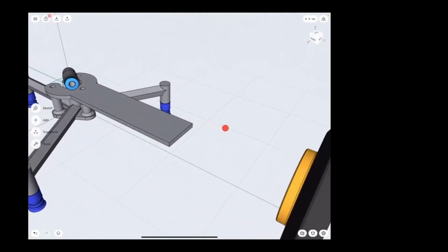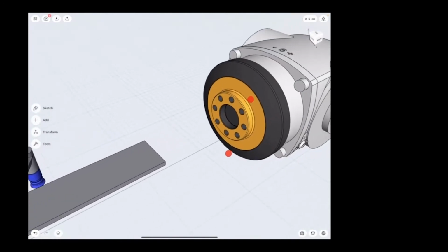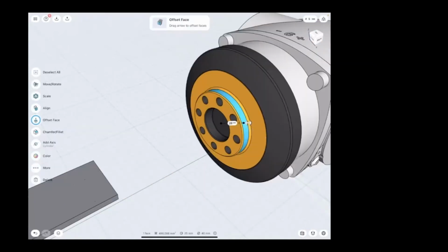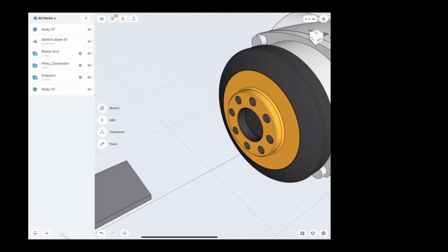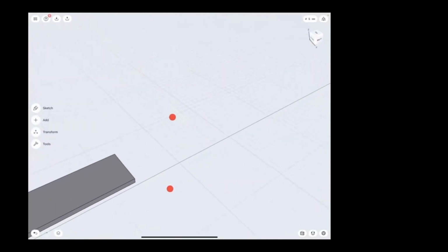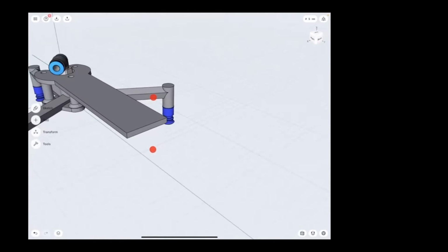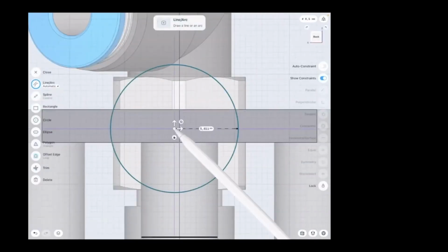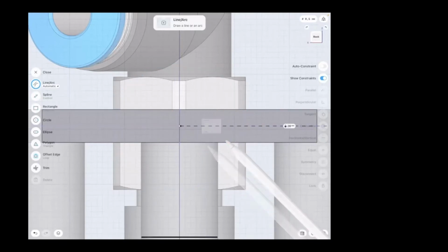And then we have arrived to the 3rd part that is designed in the workspace. The orange parts on the robotic arm are standard parts published by the manufacturer of the robotic arm to make sure that 3rd-party manufacturers are able to create accessories for their robotic arms. I will use that cylindrical shape as a reference in the following. Let me just hide the robotic arm because it will cover my view, and I'm gonna draw a sketch on that tiny planar face. It will be a simple circle with a 20mm radius.